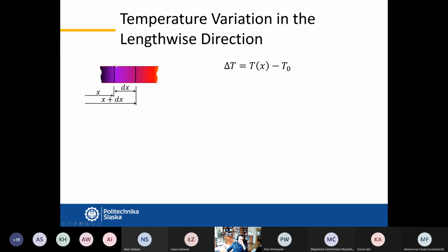If we take into account a very thin slice of material, this is from the mathematical point of view infinitesimally small, at any location of the material, this part will due to heating up move by U. So this piece of material extended from 0 to x extended by U due to change in temperature.